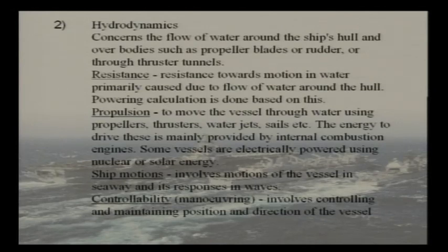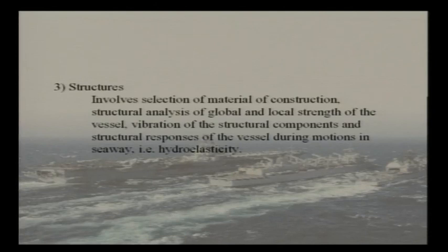So, then the next section is we deal with structures. In structures, of course, you deal with primarily what is the material to be used. Metallurgy is an important subject. You must have done already about things like yielding stress, bending stress, and at what point does a thing break, like plastic region and elastic region and all that. All those things are studied in structures. So, first of all you decide on the material, and then you design the ship in such a way that the total stress is always less than that maximum stress where it breaks or it becomes plastic.